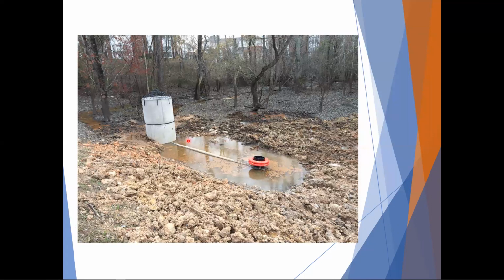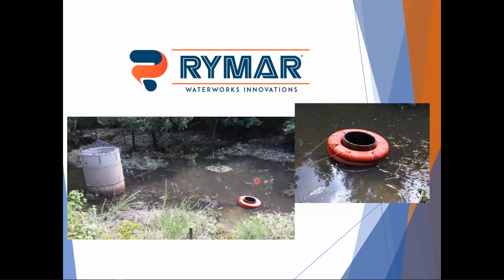The big advantage here in Charlotte was they were also eligible for some stormwater fee credits. And so by putting in this skimmer design, we got them a 95% stormwater fee credit, which translates to about $25,000 to $30,000 a year. And so even though this was not cheap work to get done, the fee credits paid for it in about 1.5 years, 2 years. And now that property owner is receiving a huge credit on their stormwater bills every year just for maintaining this.